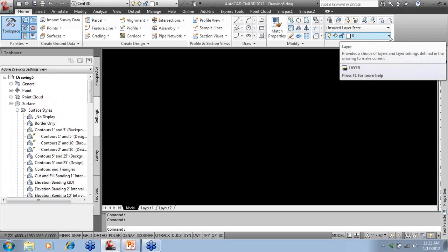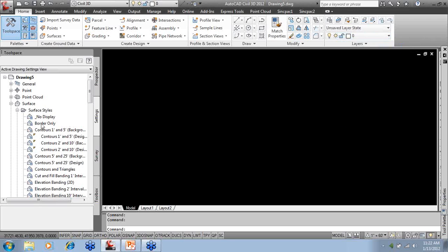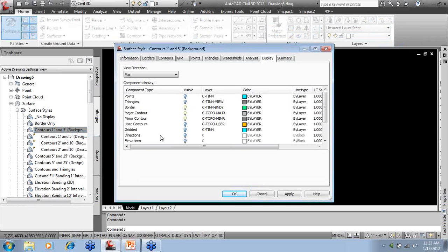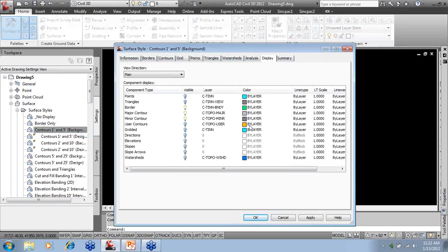The problem with the National CAD Standard template is, if I told you just to start using this, you would, and the problem is it has all these layers already configured into it. This gets very messy. As we take a look at a simple surface style, you'll notice that they also went in here and got very elaborate, and they put everything to do with the surface style.